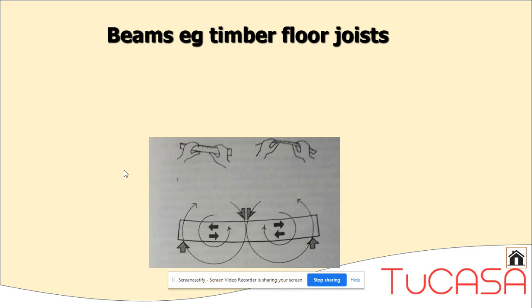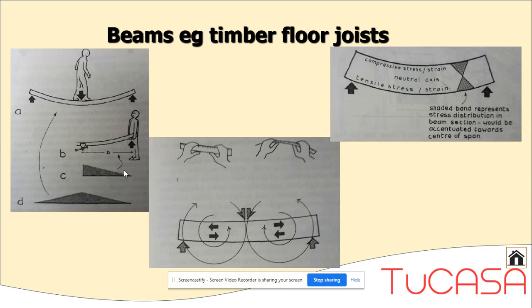Now, beams, going back to sort of structural principles, I'm demonstrating in these little illustrations here some structural principles of timber floor construction. We like to lay out floor joists and any roof beams the shortest spanning distance across the walls in our construction, and they're fixed so that they don't twist.